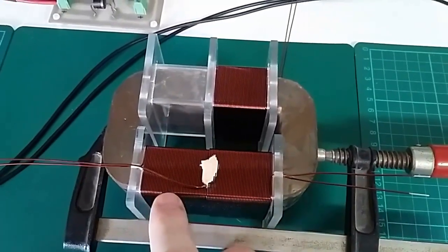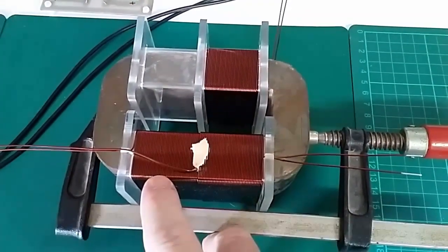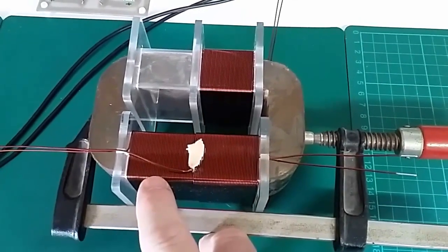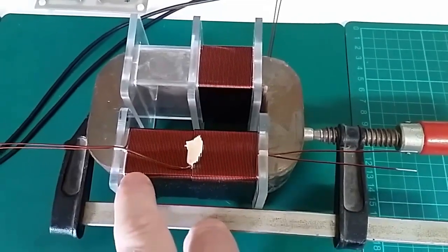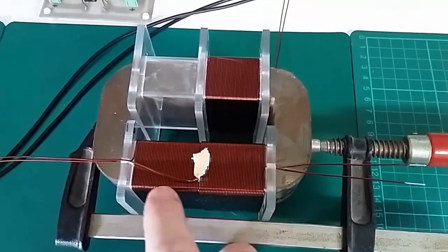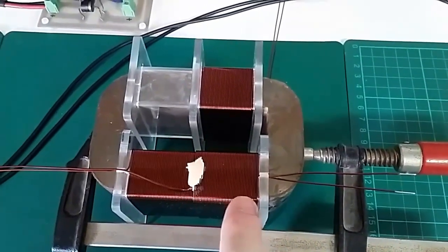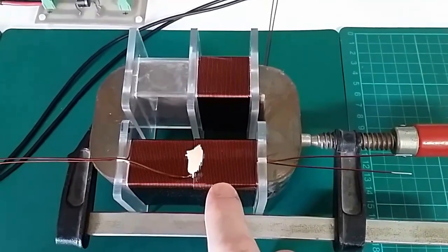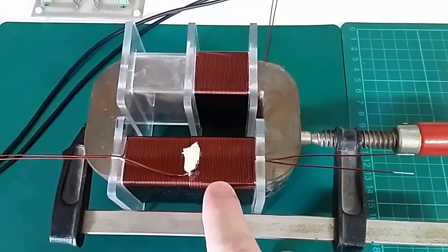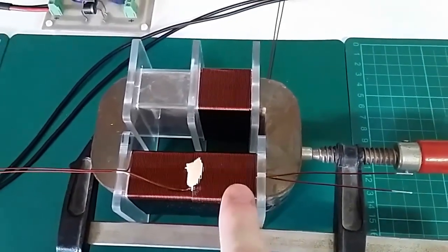These here are my secondary coils. I'm running with an Andrei Melnichenko type configuration at the moment. On the website, it shows that this layer here, the bottom layer, has 84 turns. This second layer up is only half the size. Off the top of my head I forget, half of 84, which is, I think it's 43 turns.